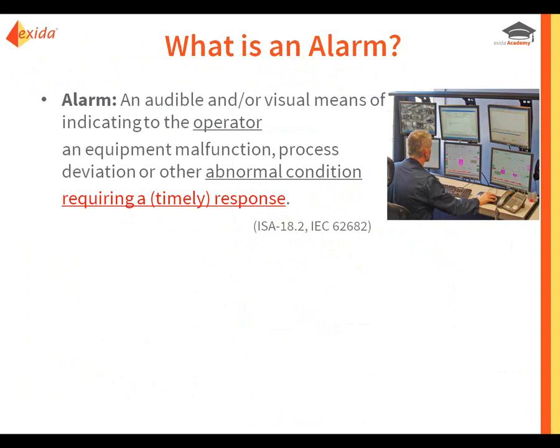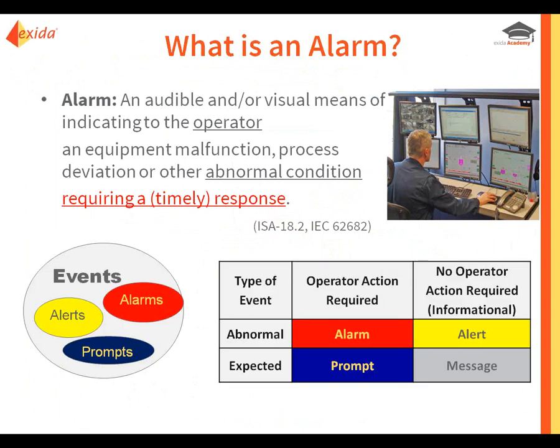The word timely has actually just been added newly in the IEC standard to the definition of an alarm. Part of the idea with this definition is so we can optimize the performance of our alarm systems and make sure that operators only get these things that we categorize as alarms. Alarm performance problems come into play when they get things that are called alarms but don't really meet this strict definition or this strict criteria.